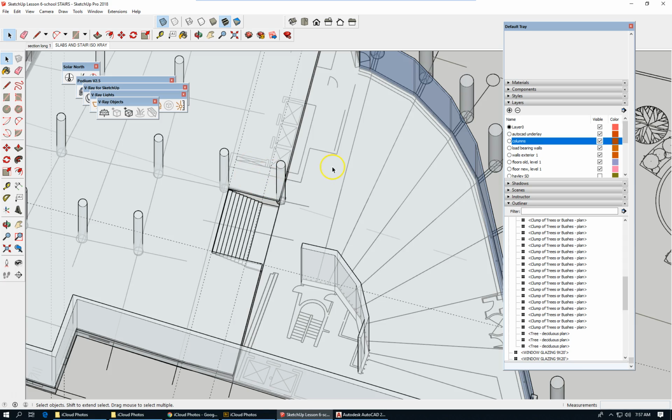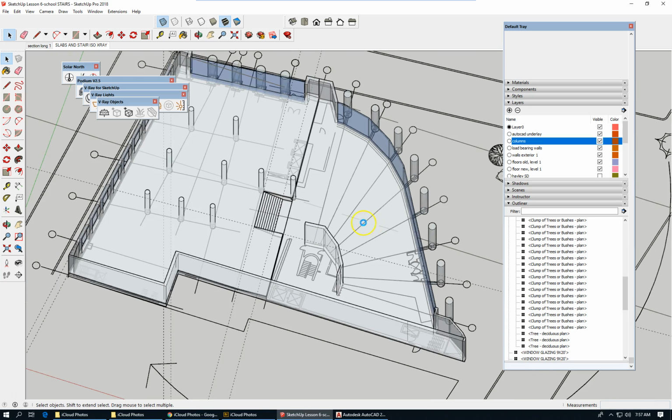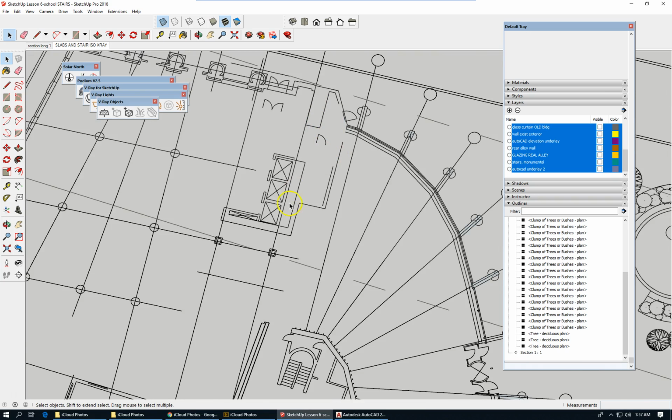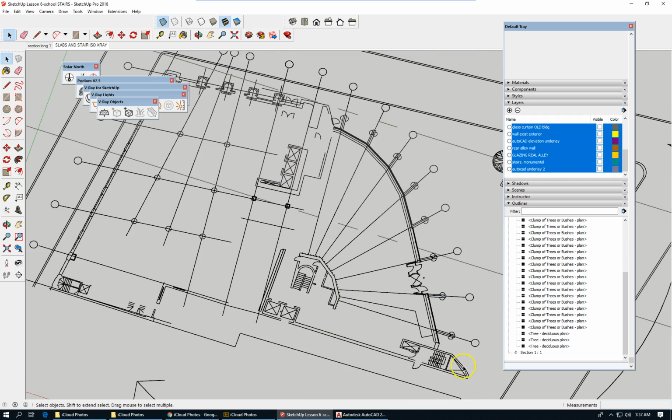So what I'm going to do is start creating some walls according to those outlines, and then I'm going to raise them, extrude them to a height of 28 feet. I'm just building out up to that third level. So I'm going to go ahead and hide the visibility of all the rest of this stuff and start to outline the walls that house the vertical circulation.